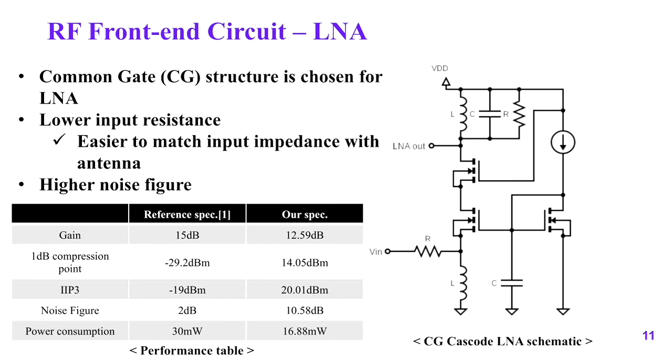So that's why, if you see the table, especially when we compare with recent designs, we give up the rest of the performance but focus on the linearity, such as P1 dB or maybe IIP3. As you compare those two numbers, you can see that the linearity of the LNA shows a higher performance.